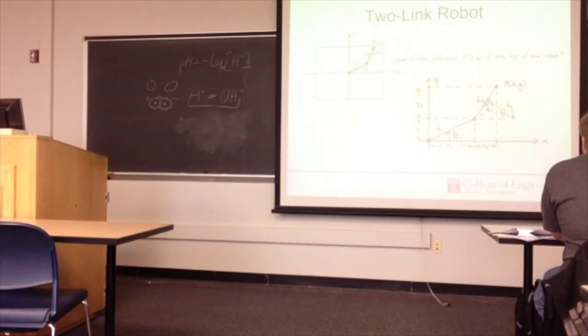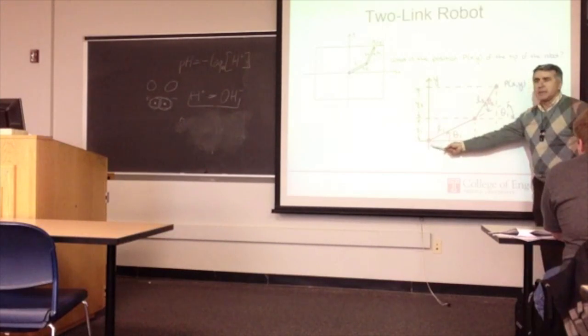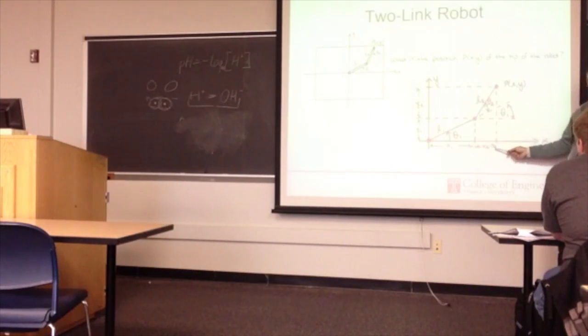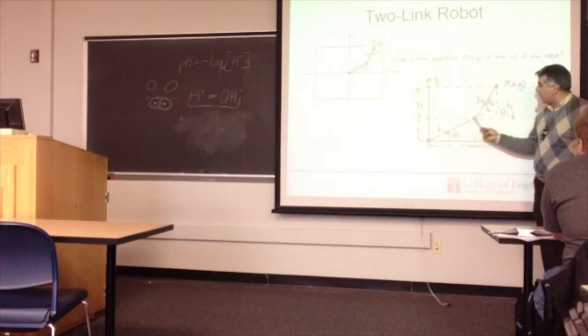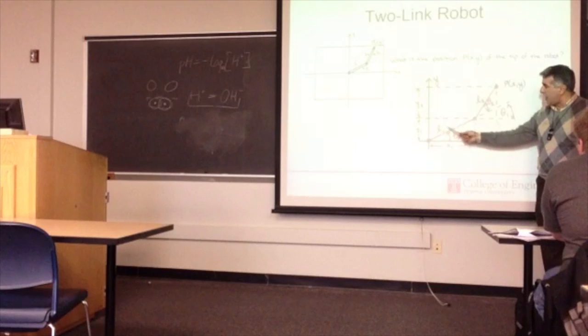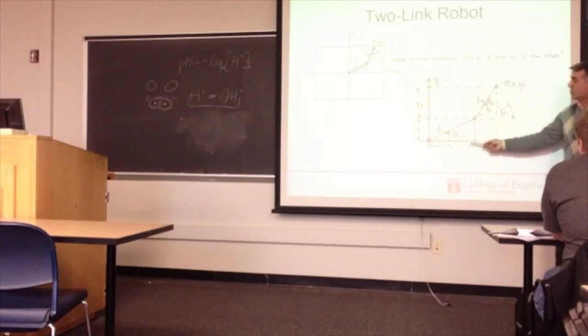Yes? You can get a big P up there. You can get the, yeah. So, in other words, look at this diagram. Theta 2 is the angle that the second arm makes with this first link. Okay? So, in order for us to know where P is, I need to know this distance, and I need to know that distance, right? This distance we can easily find from the first bar. I know theta 1, I know L1. What is that distance? X1 equals to?